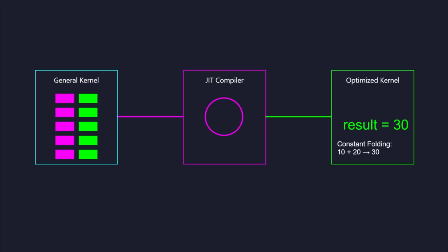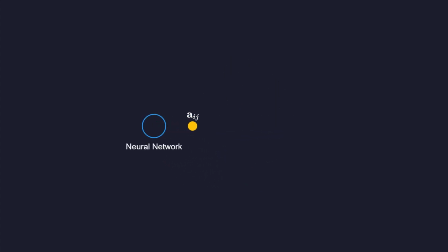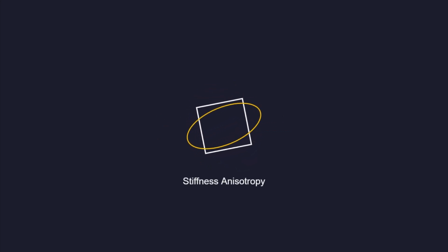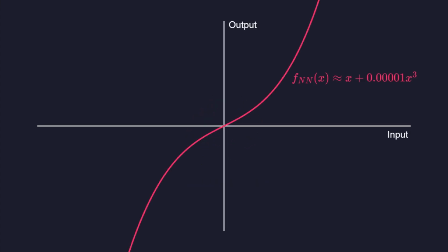To support different material parameters without rewriting code, implement just-in-time compilation. Compile the specific kernel for the current material properties at runtime to allow the compiler to perform aggressive constant folding optimizations. For materials like fiber-reinforced polymers, the network must account for orientation. Pass the orientation tensors as invariant inputs to the network. This ensures the model predicts the correct directional stiffness as the mesh rotates during simulation.